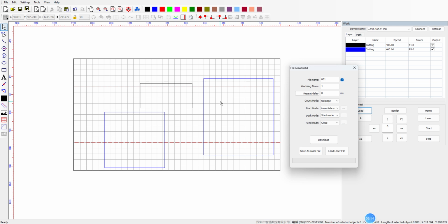That's easier if you put the fabric closer to the right or closer to the left. We just move the laser head a little left or a little right, just inside the fabric, and it will start to cut. But we don't move the laser head lower too much. If it's too low, maybe the bottom line is already over the frame. It's going to show you it is beyond the working area. Then we move the laser head back a little bit more and click start to see if it works. If it doesn't work, we go back a little bit more. So that's the immediate working mode. It has priority by the laser head stopping at the top right of the process file.